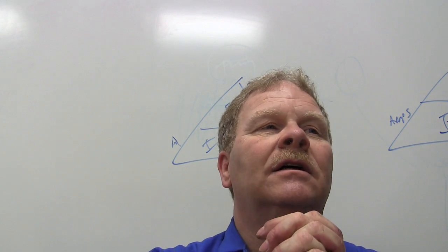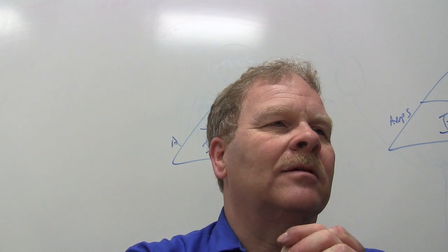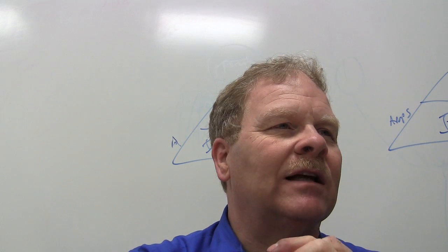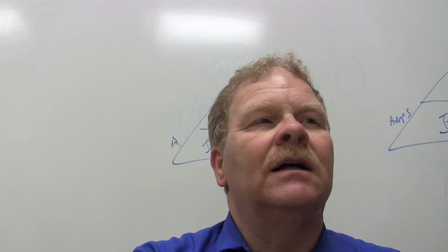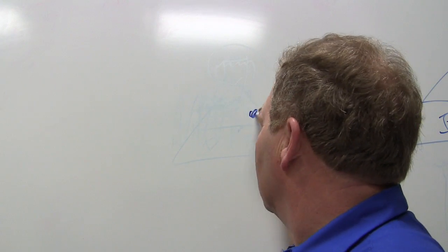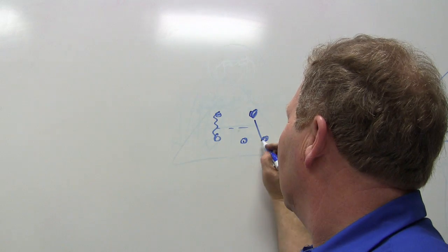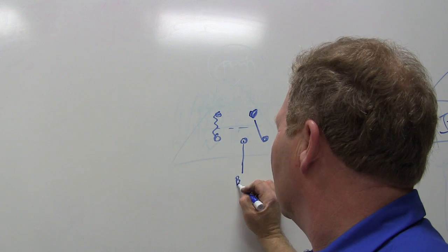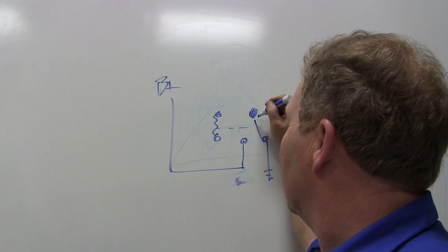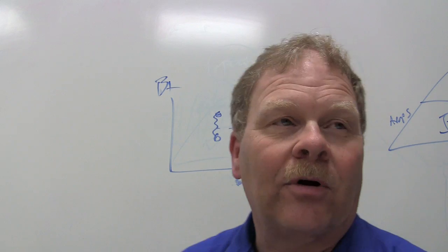But the only problem with those is they're not measuring current flow. I mean, they're not measuring available current. They're only measuring available voltage. And I ran into a problem one time years ago, and I talk about it occasionally because it illustrates what I'm talking about. I was taking the Ford service manual and I was working on an ABS system that had an anti-lock brake light on. And there's a relay in there, wired up on that particular car, where you've got your common, your normally closed, your normally open. This is your coil. This was B plus, and this right here was ground. So when that relay was at rest, this was grounded. And whenever you energized it, this was powered up, and it was part of the ABS system.